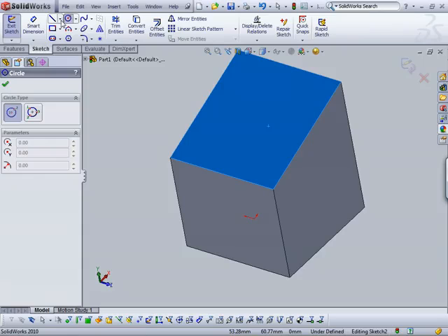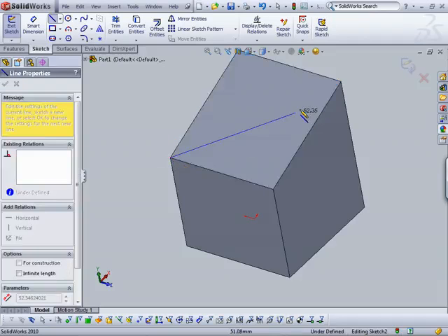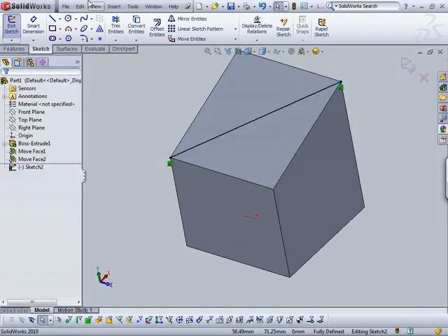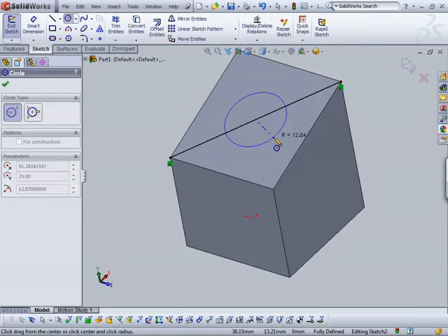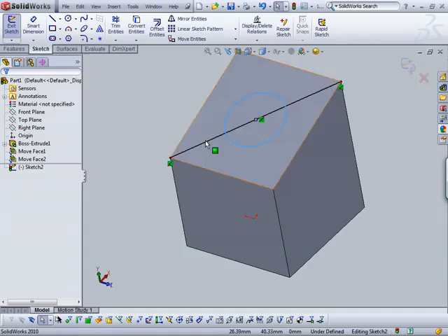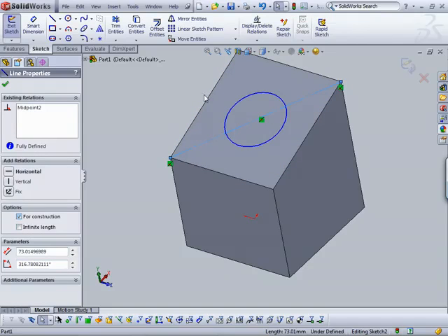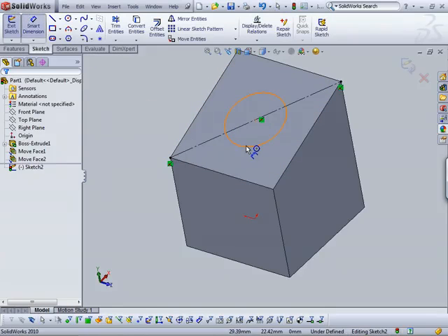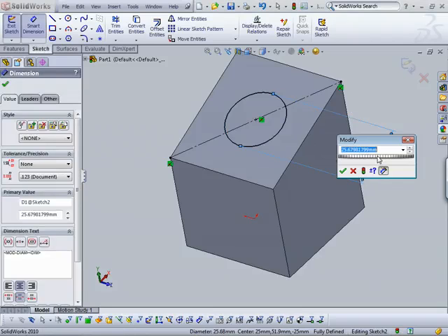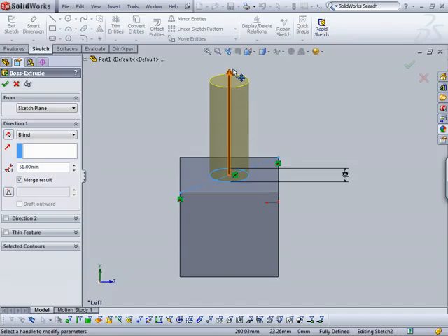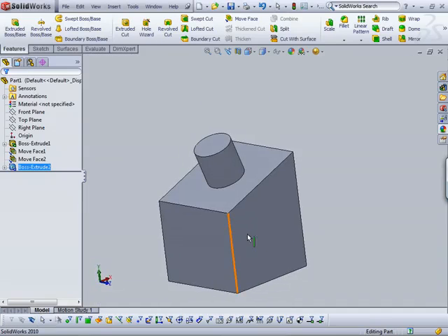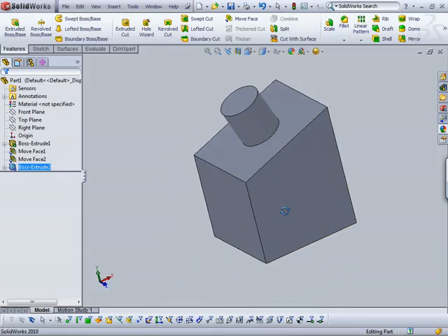And if I wanted to make it in the center, I could snap a line to either end of this rectangle, snap to the midpoint. I'd set this line to construction line and set a dimension for my circle to 20 millimeters. Enter. And I just choose how far I want it to go. Okay. Now even with that there, I can still change faces.